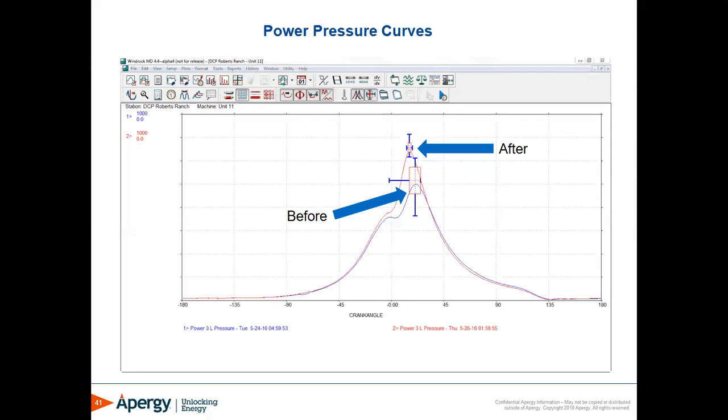The fuel valves have a long life as well if the engine stays healthy. Now, if there's detonation and say the flame front goes back through the piping and burns up the fuel valve, which we've seen a couple of times, obviously then you have to change out a fuel valve. But if the engine stays healthy, you're using the system correctly as it's identifying issues, you're fixing them, then the chances of that happening are fairly low.